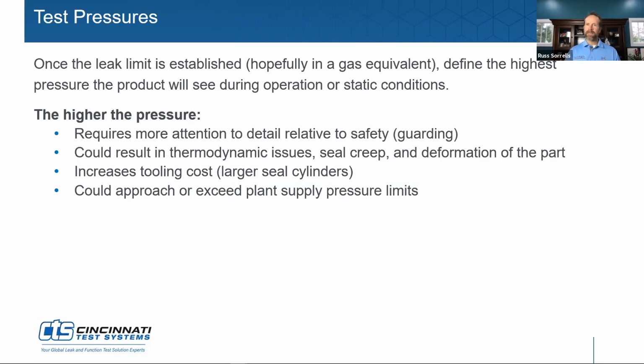And they were applying a pressure loss over time, so it could only lose X amount of psi during the test. And what I helped them to understand through the formulas that we've got on our website is that they were testing one product to a more stringent test than they were testing their other product. And so that's the importance of identifying a flow rate as opposed to using a pressure loss, because the volume of the product is going to have an impact regarding the leak rate.